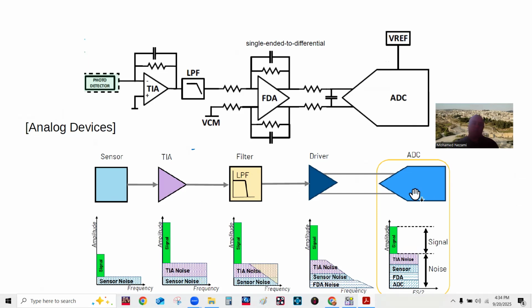We're going to start looking at the noise contributors to the signal in the DSP domain, and that really comes in from the reference voltage. This guy puts noise into here, this guy puts noise, and there's thermal noise from the outside. We've got the KTB noise of the system that comes from the outside. Then we have the noise that is internally generated within these active devices, and then we have the spectral noise density of the ADC. Take all of these and combine them with the square root of the mean squared for all of them, because as you know, these are non-coherent noise sources, so the power adds up in mean squares, not coherently.